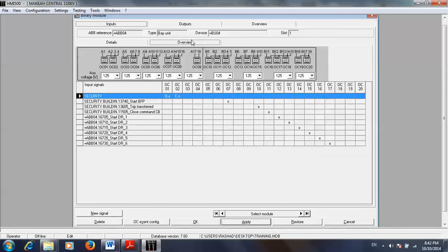If you go back again to overview, you'll find this binary input is available here. And then in the same way you can add the other bus disconnector and the circuit breaker. Actually you'll find this configuration almost right, but you have to check it against your scheme. For example, for disconnector D613, the open status is binary input number 1, closed status number 2, and so on for all other binary inputs.